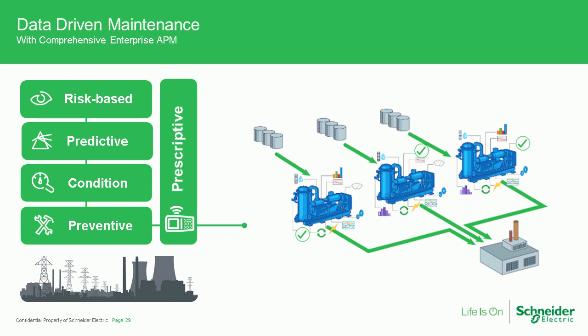Predictive, which is really a longer horizon. Predictive maintenance looks at the overall operating envelope of an asset, and statistically and through pattern recognition and machine learning, models the operating envelope of that asset over many, many different operating conditions, and can provide alerts to say, hey, we're not seeing the asset react to its current operating condition the way it usually does.